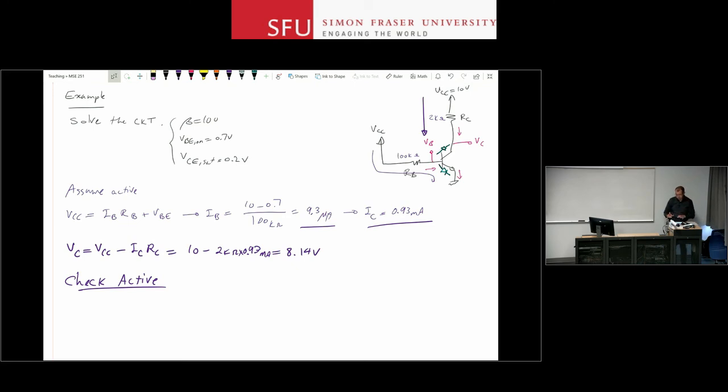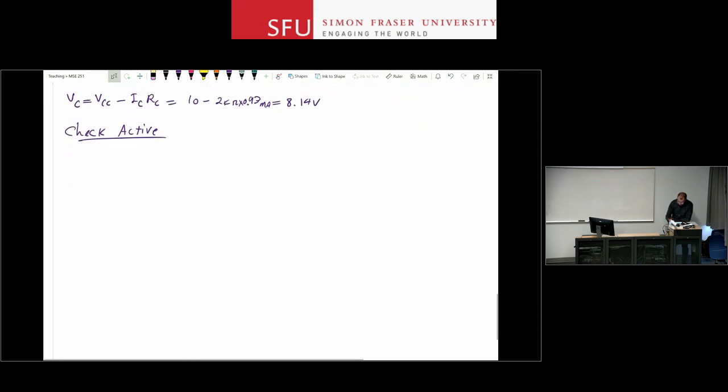And let me turn it into a problem that is going to be in saturation. Same circuit. I'm going to change RC. Now, instead of 2 kilo ohms, I'm going to use 20 kilo ohms here. Let's say plus 10 up here, and then over here. Same circuit, right? Plus 10. And I do the same.